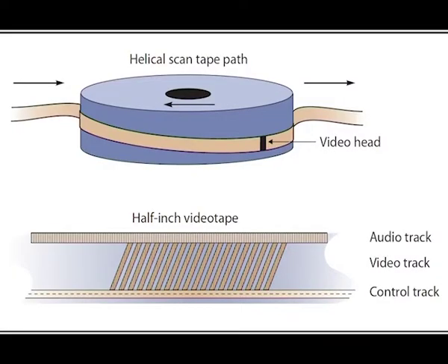Analog video. In an analog system, the output of the CCD is processed by the camera into 3 channels of color information and synchronization pulses, and the signals are recorded onto magnetic tape. There are several video standards for managing analog CCD output, each dealing with the amount of separation between the components. The more separation of the color information, the higher the quality of the image and the more expensive the equipment.